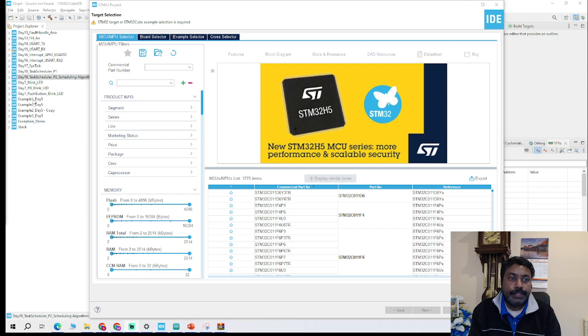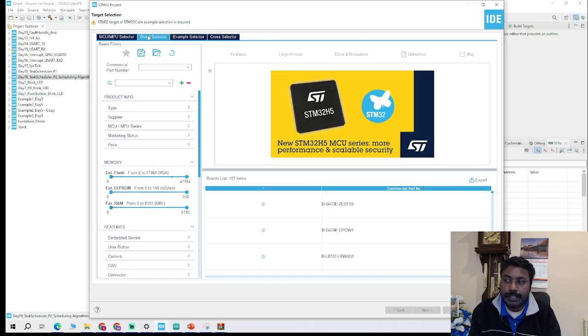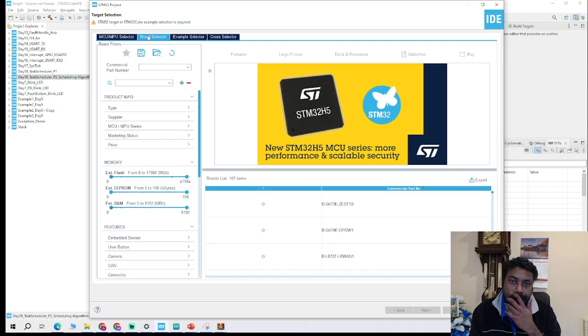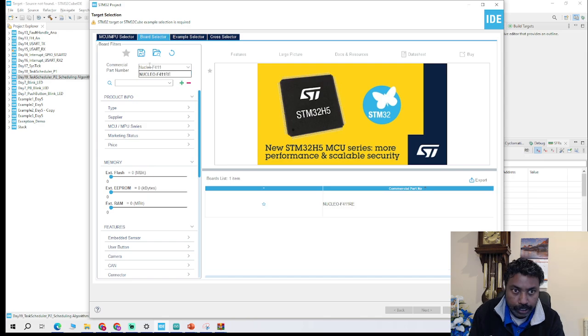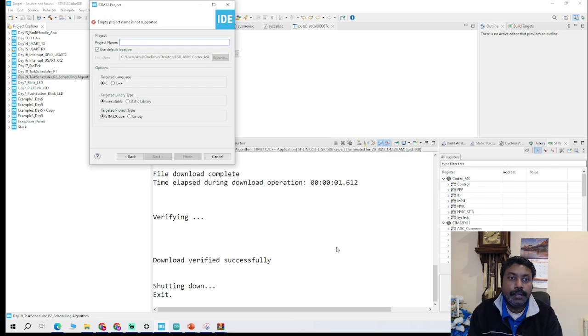So first step, as you know, you need to go to the board selector. You need to choose which board you are targeting. So Nucleo F411RE, choose that board, select it and hit next. Then give a project name. We are on day 20, so I will give it as Day 20 ADC. And we're starting from scratch, so click empty and then finish.